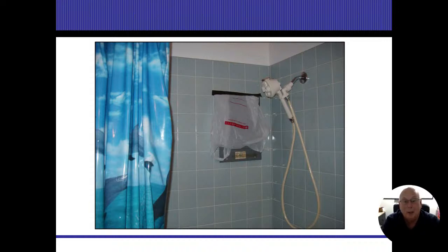And granted, we don't want to let any water get in there. That's true. But more realistically, just putting the plastic over it isn't really going to protect anything. It's the humidity. If that humidity starts getting into that panel, it causes things to rust. Rust is resistance. Resistance creates heat. And that's when we start getting into problems with our electrical panel.